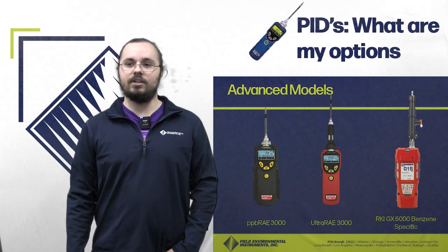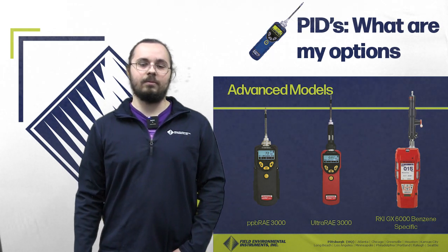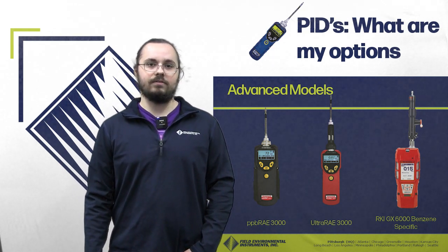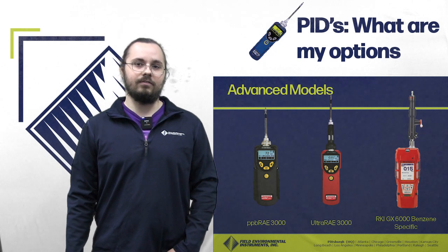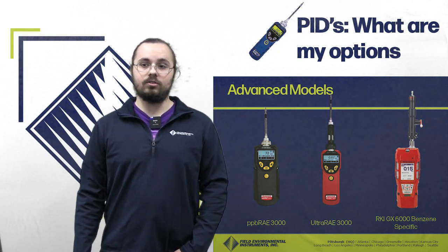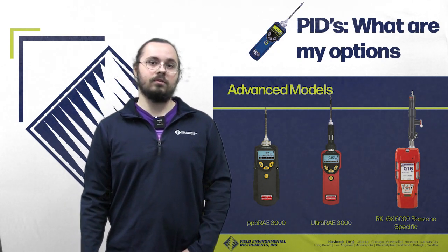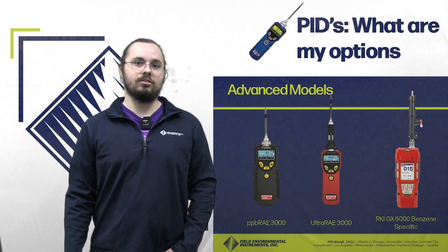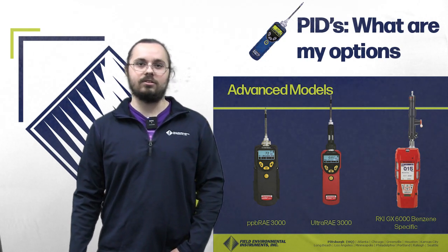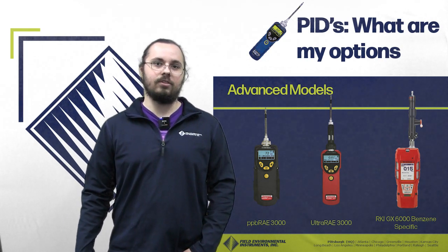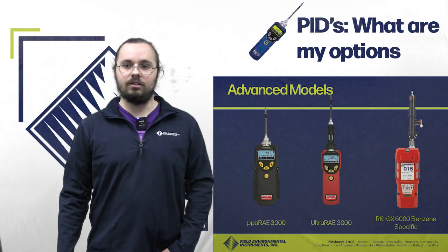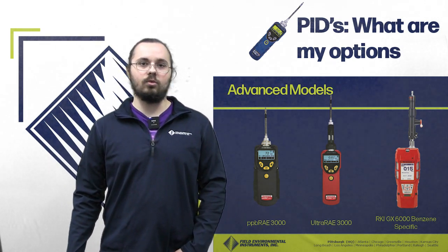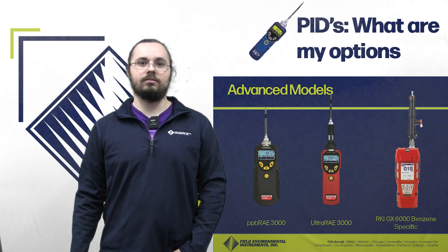The RKI GX6000 benzene specific is very similar in that it's also used for benzene detection. It has the same feature where you can drop a benzene tube into the unit to filter out all other compounds and give you benzene readings. It also has 2 interchangeable smart sensor slots, which allow you to slot in other PID sensors to use in tandem with the benzene sensor. This also comes with a 10.6 or 10.0 eV lamp.